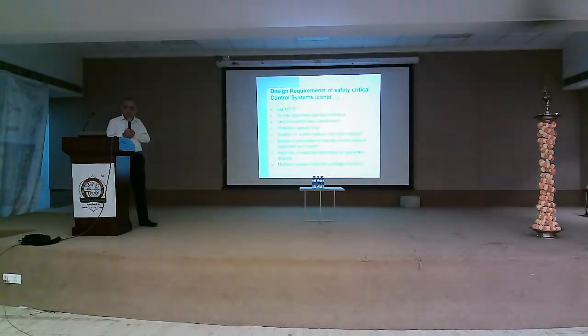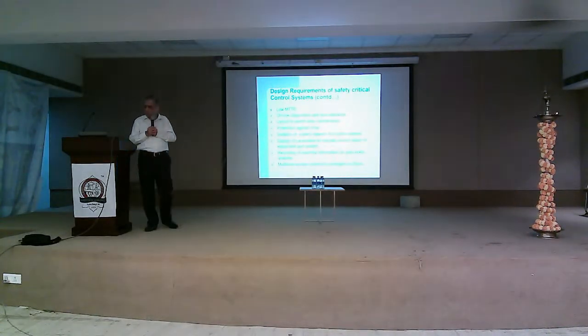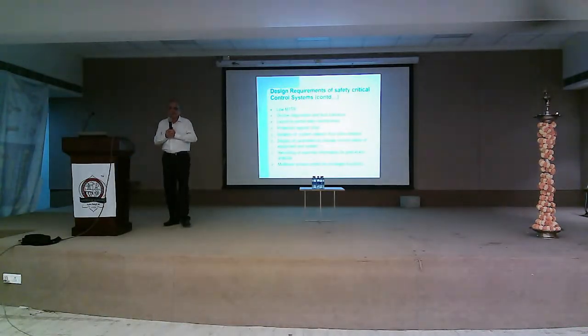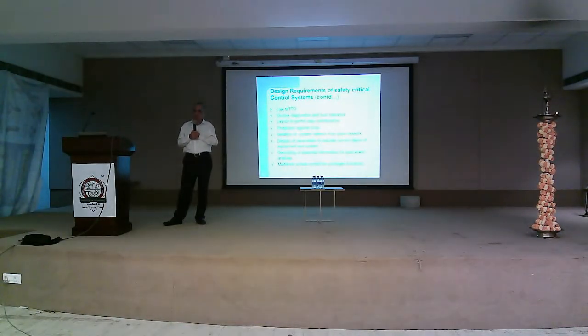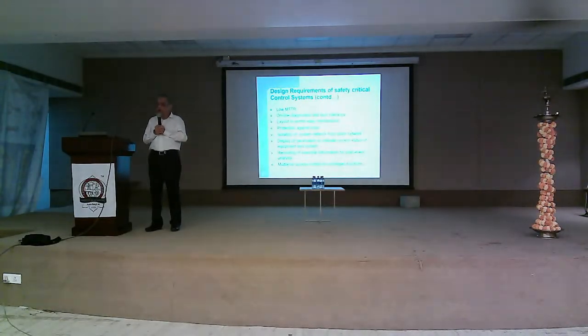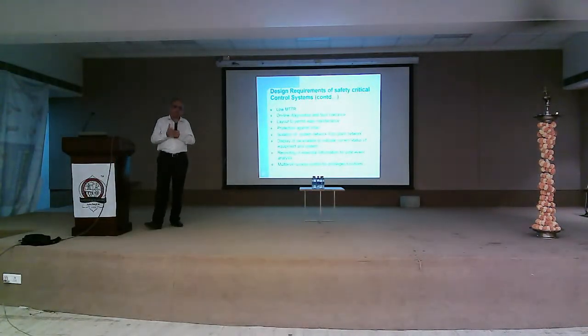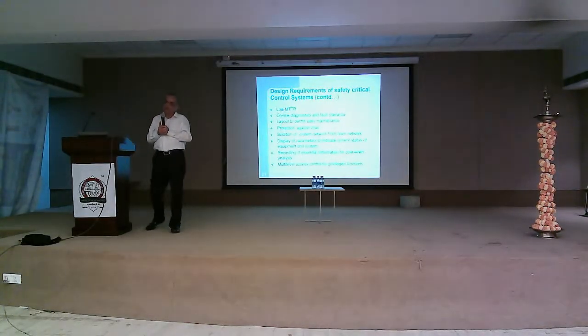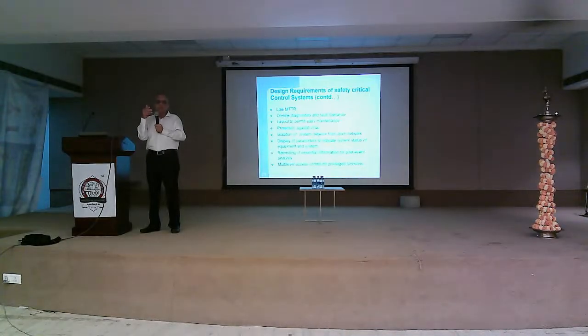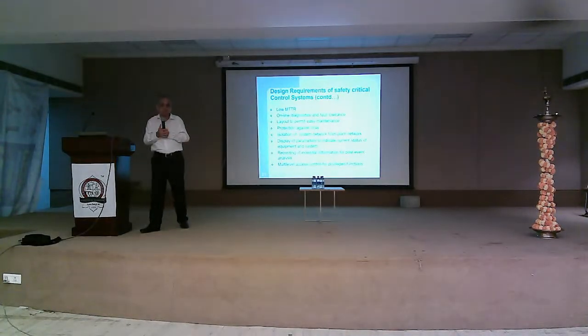There is a low MTTR, mean time to repair. As I told, we design the system in which you should be able to remove the faulty board even online. So it has to be pluggable type, first thing. Since it is pluggable, if you remove any pluggable thing, it is likely to fail.